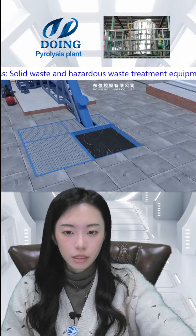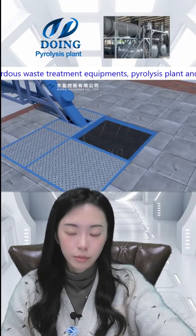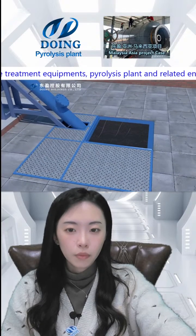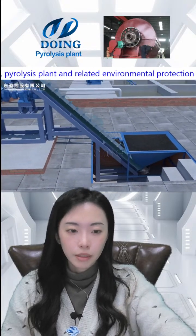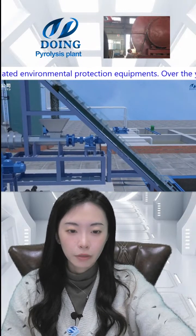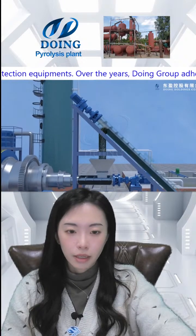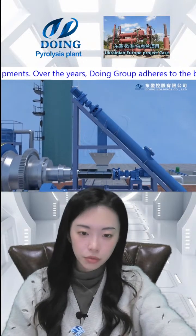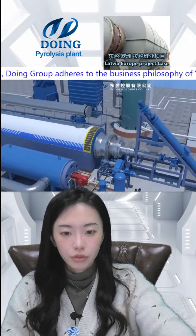The first is the feeding system. We need a pre-process to turn the waste tire into rubber powder. With a diameter of less than 1 to 2 millimeters, the rubber powder is conveyed to the horizontal feeding section by this rubber powder lifting screw conveyor. Then it is pushed into the reactor for heating.